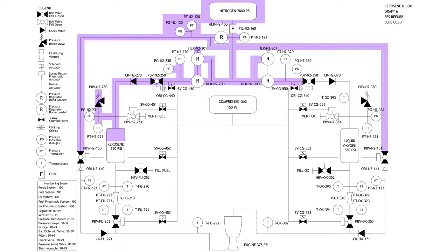Yeah, because isn't that what comes from the... Yes, you are going to close 251 when you switch off to pressurized? When you start pressurizing your system, you need it to be a closed system. Otherwise, you're going to evacuate all your gases and waste pressurizing gas. Good question. Okay, so now we created basically, if we'll just take kerosene by itself, a propellant